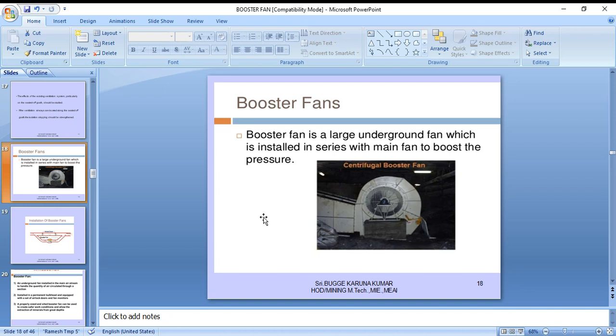Booster fans have been widely employed in non-coal mines. However, the trend of mine regulation legislation is towards bringing non-coal mining regulation closer to those for coal mining, thereby precluding the installation of main or booster fans underground where not permitted. A booster fan may be used effectively on a high resistance split to reduce the overall pressure drop across a parallel circuit that the primary fan must overcome.